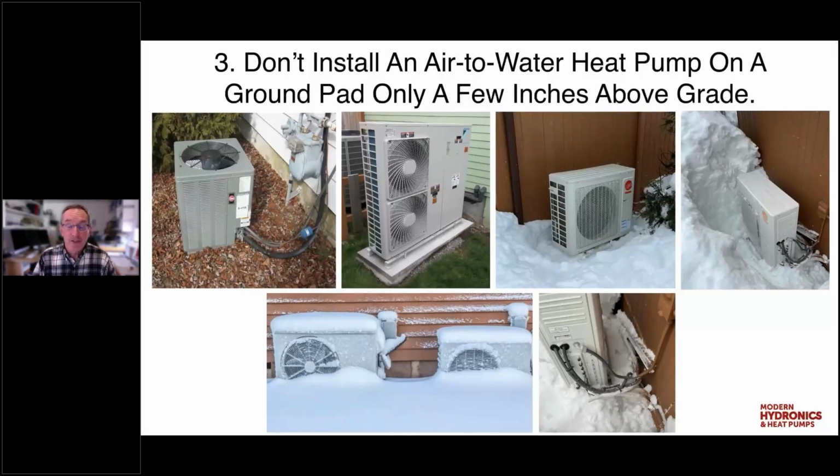Here's a heat pump that's actually on a stand. That stand is about, I'd say it's about 16 inches tall. This is in upstate New York. This was a unit that was completely buried in snow this winter. Over here on the far right, you can see another picture. I literally dug that unit out of that snow with a shovel. And you can see that the line sets would have been covered with snow. You can see some damage to the channel that the line sets were routed in.